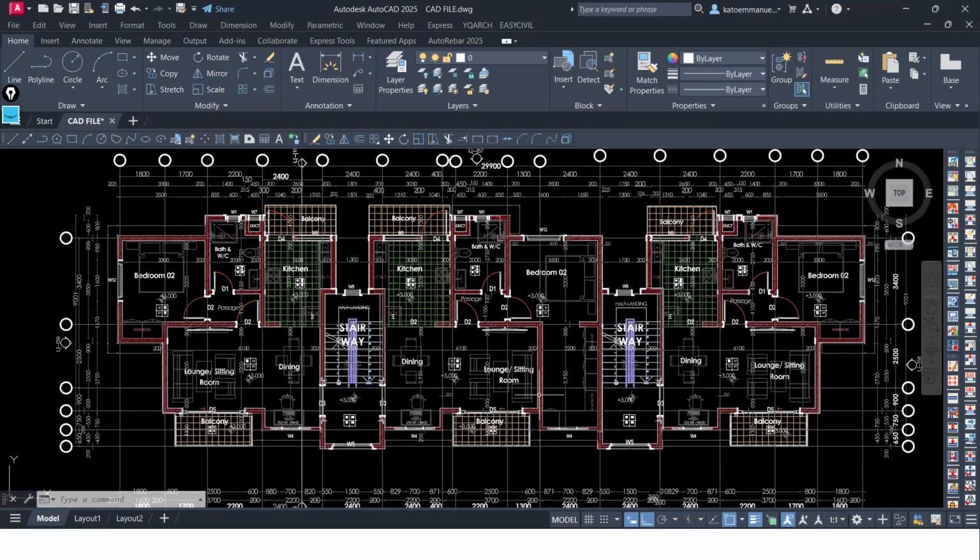When we are designing slabs, we don't design for the ground floor slab, unless there's a basement below. If there's a basement below, then you design that slab. But if it is going to be a slab on grade, where you are putting hardcore, oversight concrete, and BRC, there we don't design that slab.